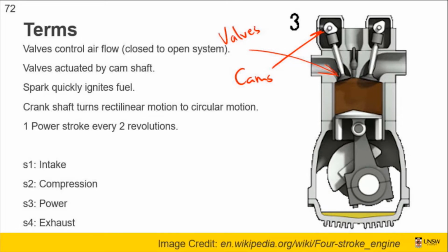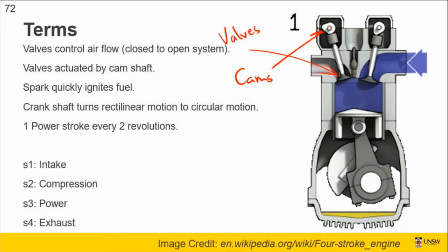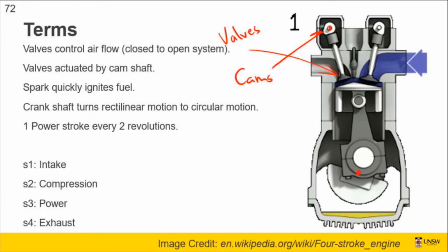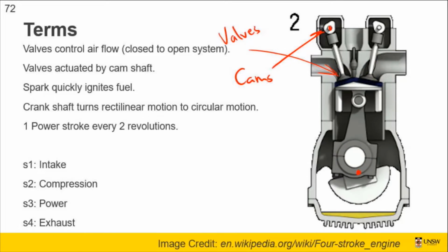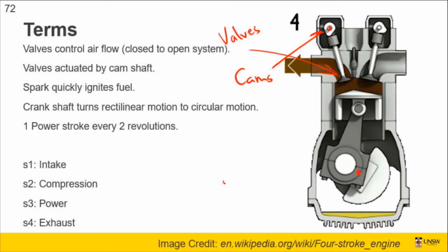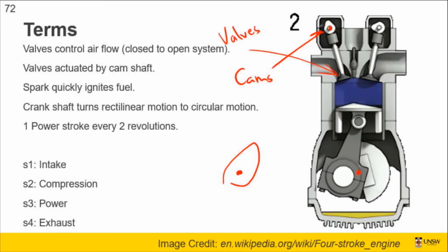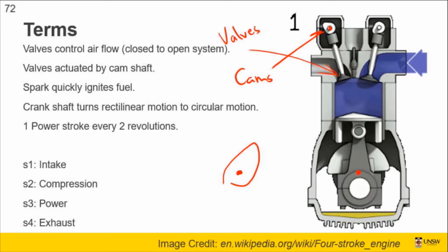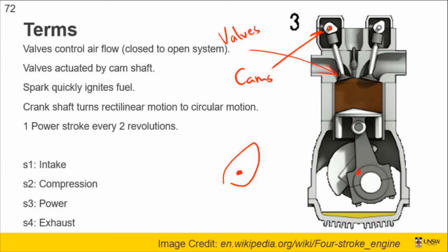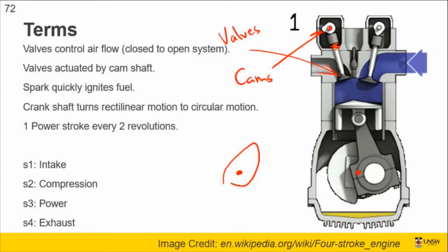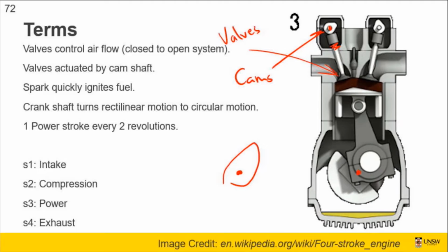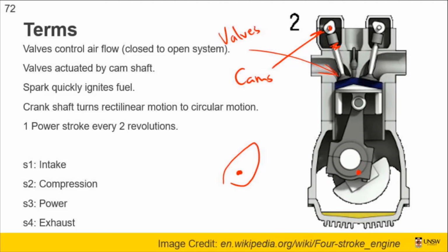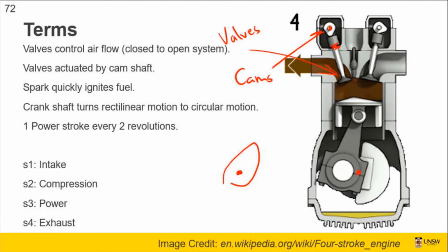So the idea here is that you've got this shaft which is turning, and it's related to when this shaft turns. So you've got a timing belt joining the 2 of them, and as this eccentric cam rotates around, it'll push on that valve and open it up, and then you'll have a spring, not shown, but the spring will be there. Right? You'll have a spring that will return the valve to its home position. Okay? So valves are controlling the flow in and out of the system. The valves are actually driven by a cam.